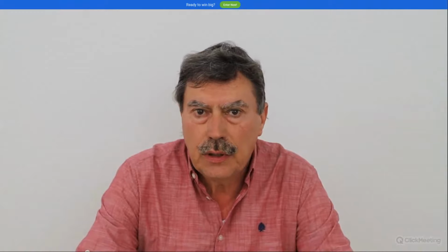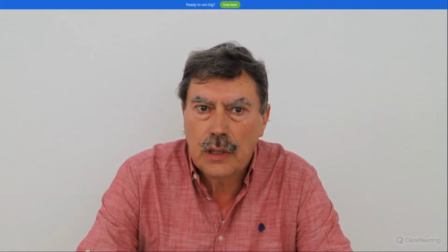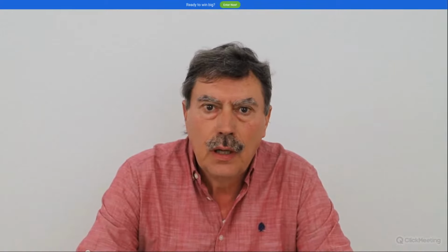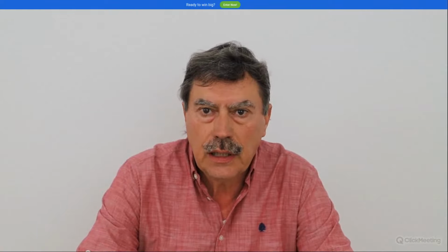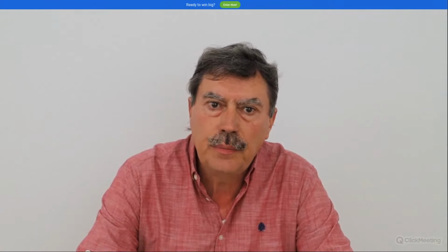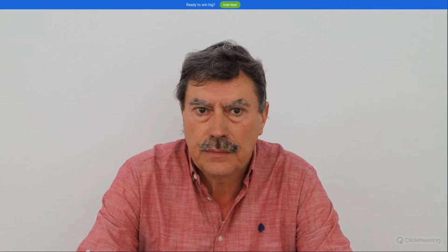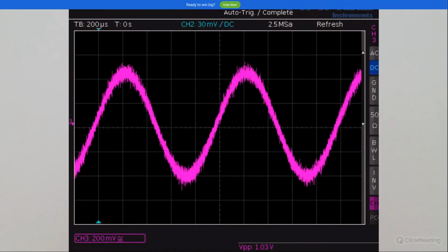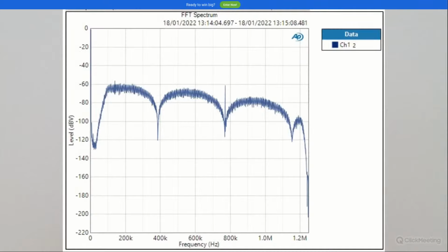Generate a sine with your audio interface and have a look at it with your scope. If you see a clean signal, like I see with my RME, the amp behind the DAC includes a filter. If it looks like this at the Behringer UMC 202 HD, there is no filter. This is the spectrum measured with the 1 megasample digitizer of an APX555.